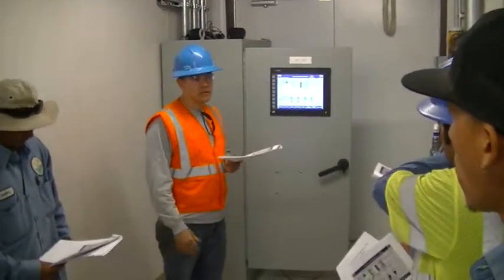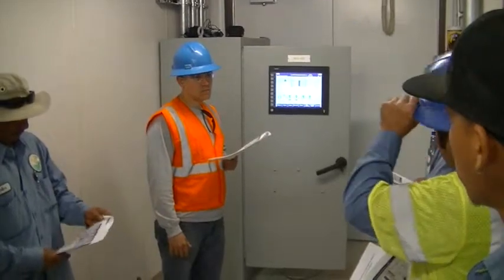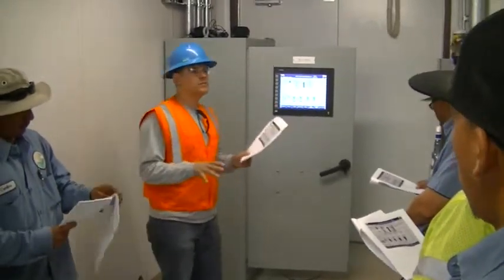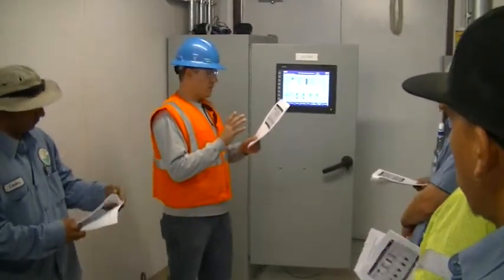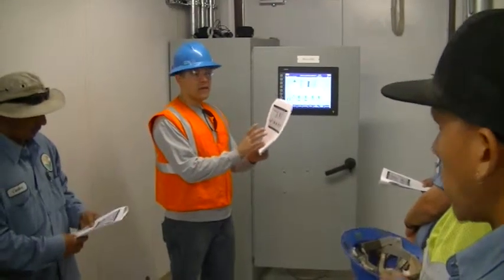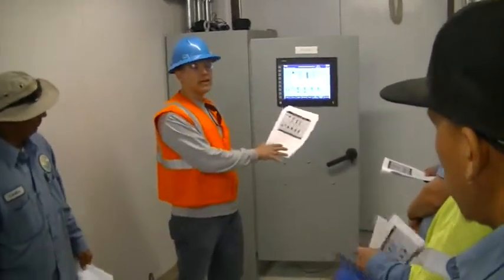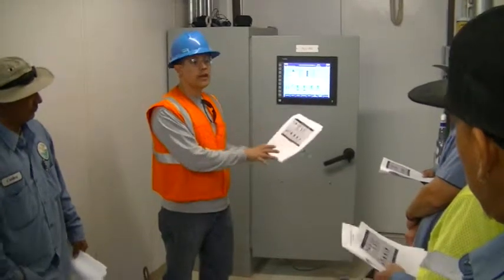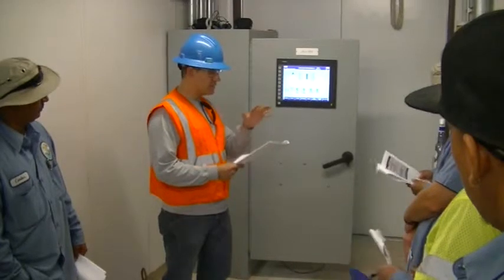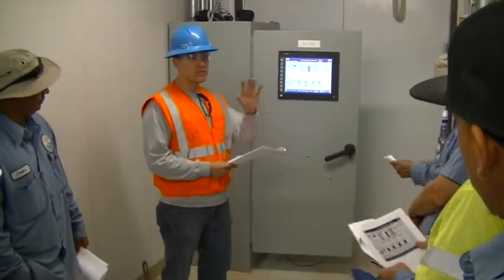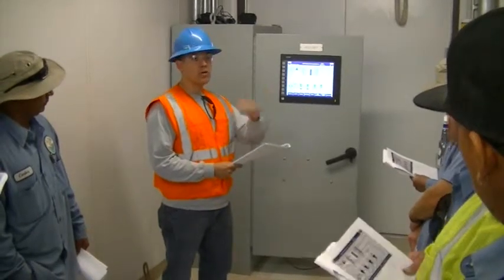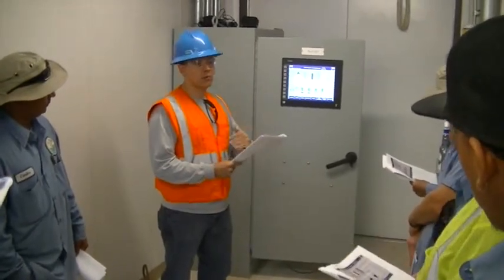Right, so what you're saying is if the pressure out there fails and gets too low, then... Well, it's two different systems. You basically have the pressure gauge, the analog one that's out there, the PIT. And then we have Mercoid switches, which are the mechanical ones. Those are the backups. So either one of those can put it into the backup mode. Basically, if we lose our signal from the pressure out there, or the Mercoids drop below their set point pressure, they'll put it into that mode.